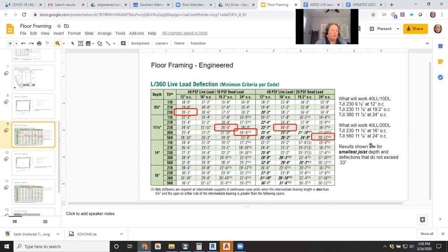Like it will say, for instance, what's the span range for floor trusses, and span ranges for nominal wood, and span ranges for steel and stuff like that, but it won't tell you specifically what's the exact span this can do at this size. That's manufacturer's specifications, or the Wood Council has to tell you that. Those are those span charts that we're using, okay?